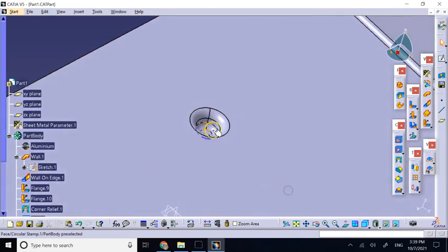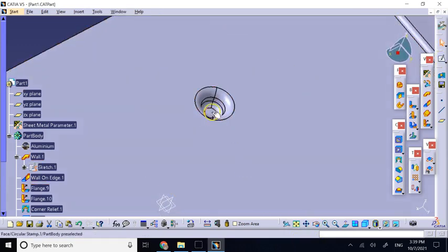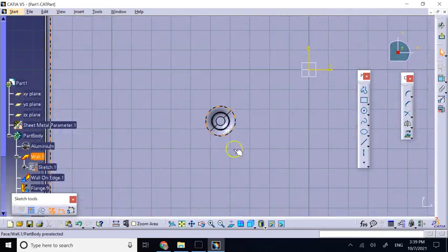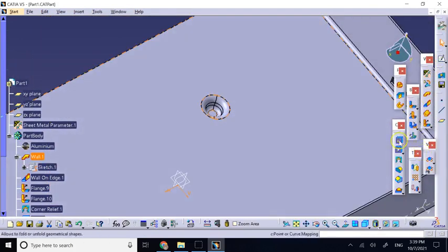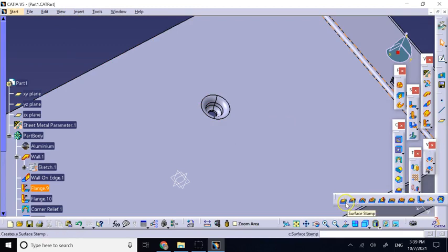If I want to create the hole at the end, then I can definitely use the cut extrude or the hole command and get rid of that bottom portion of it, right? So it's no big deal. I can just go and, as I told you, select this face, go to sketch, choose this, project it, get out, and just cut extrude it. Just like that. Done.